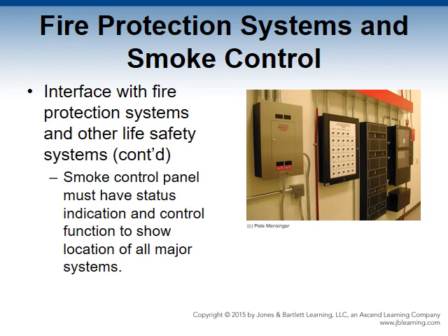Smoke control systems require both normal and emergency power sources. If the primary power source is lost, they can continue to run. When emergency power is provided, all components of the system must be reliable and functioning. The functioning components of a smoke control system always require monitoring to indicate the status of all equipment. Operational controls are also required for each smoke zone.